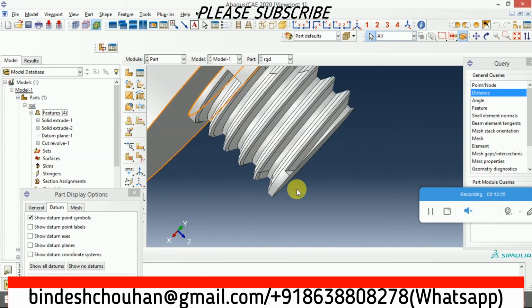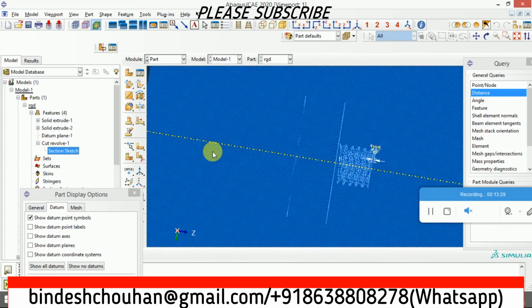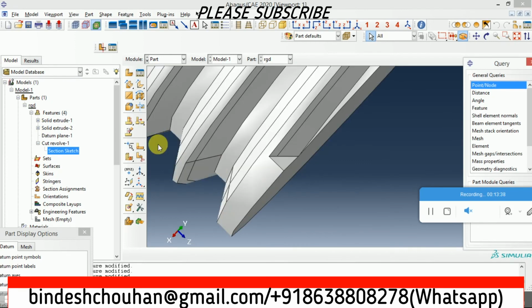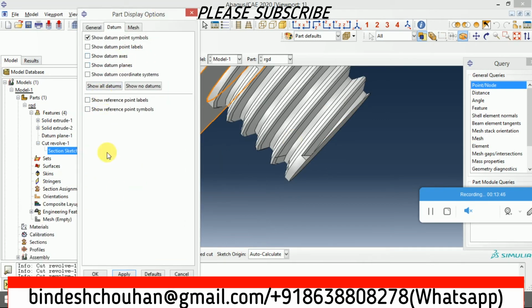Now I also want to get rid of this, so what I'll do is, I'll go to this section and I'll save this section, sketch 1. Why am I doing it? Because I'll again make a revolve cut. I'll display all the points.